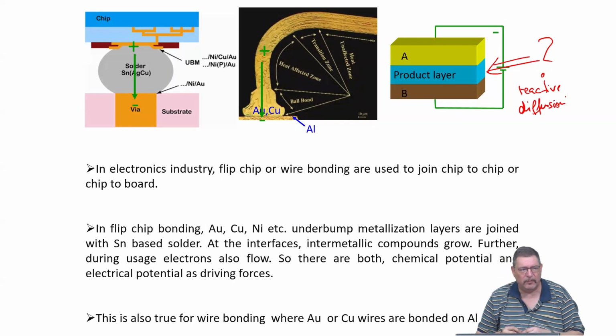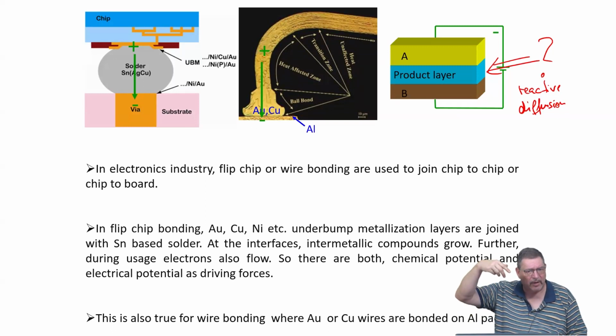Because the diffusion itself causes a phase to form, which would now affect the further diffusion behavior, because the material transferred by diffusion in this product layer is different as compared to the wire or the plate which have been connected. And this is then making the mathematical description of diffusion even more interesting, because the partial differential equation system gets larger and you have to solve it simultaneously.